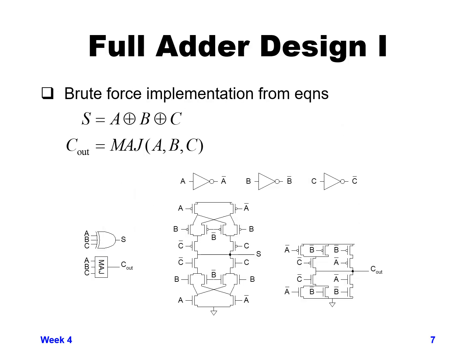On the previous slide, we had gone through the full logic function of generating a sum and carry out. The equations for those logic functions, which the logic table tells you the result of, are shown here, where the sum is going to be the XOR of A and B and carry in together. So you could either do an XOR of A and B followed by the output of that being an XOR with carry in, or you could do a full XOR of A, B, and C together in one stage.